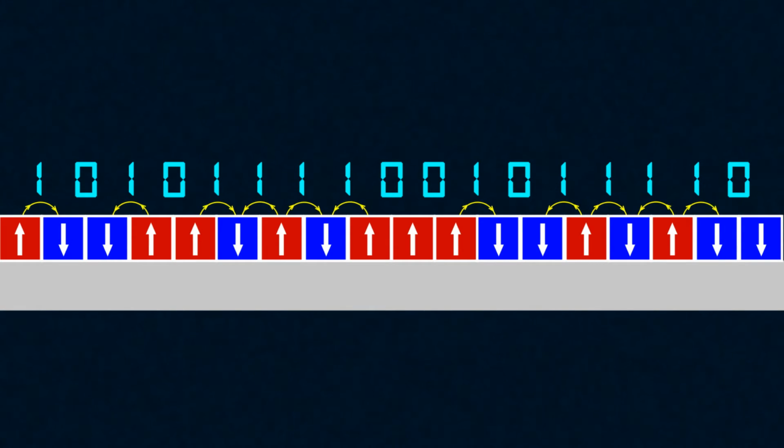That is, whether a 0 or a 1 is written on this part of the disk depends on whether the read head registers the magnetic flux between this and the next cell. That is, the data carrier is not the cells themselves, but the boundaries between them, which are also called domain walls. If there is a wall, then the magnetization of the cells differs. Then we record 1. If neighboring cells are magnetized the same way, then there is no domain wall, and we say that 0 is written.